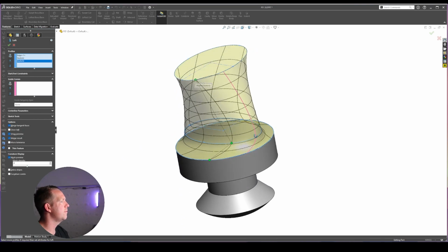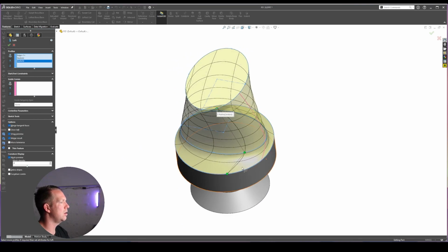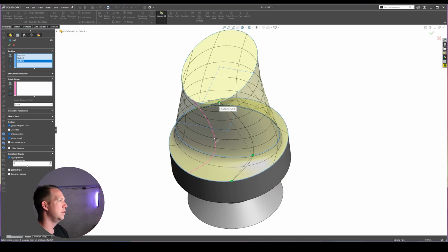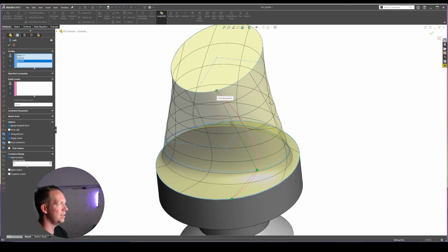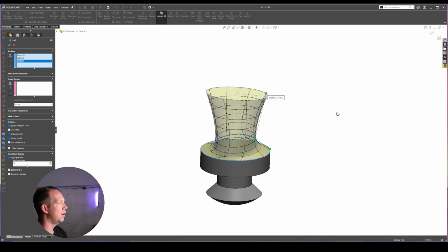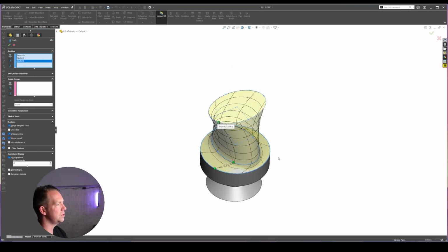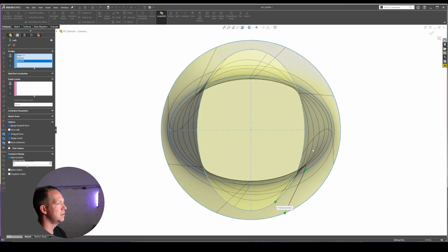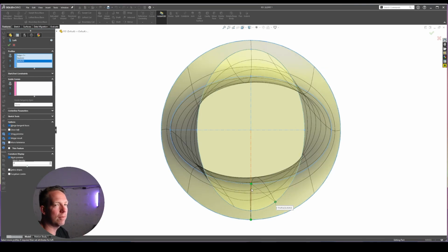Now, what we're finding is that our loft is kind of twisting. And it's twisting because of the location that we selected those profiles. It is controlled by these green dots called connectors. Now, what we want to do if we want to achieve a nice symmetrical result is move all of those connectors to either a vertical or horizontal line so they're straight. Let's try moving them to the bottom here. So just click and drag, and I'm moving it to the bottom. Now, there is a more exact way of controlling this, which is with guide curves. Well, we might look at that in a few minutes.